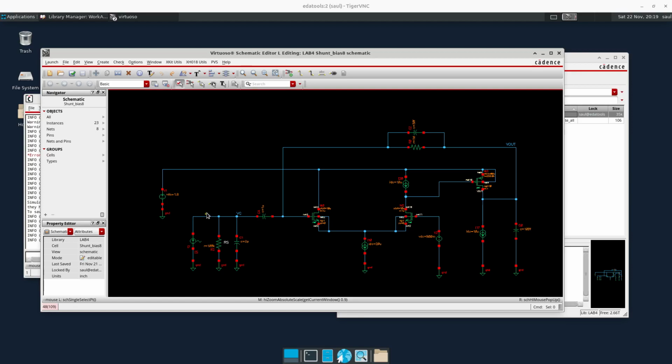When you finish moving DC voltage and current sources and simplifying the biasing network, you will end up with a circuit which has just a limited number of current sources that cannot be moved anymore. These are typically current sources that have one terminal connected to ground or connected to VDD, and DC voltage sources that have one terminal connected to ground, that are typically voltage references or the power supply.